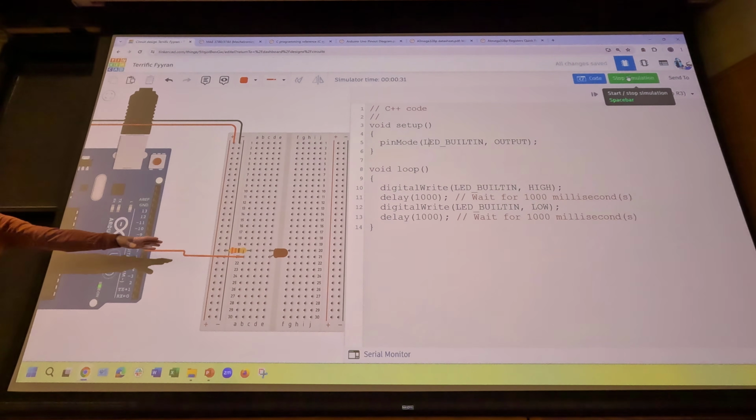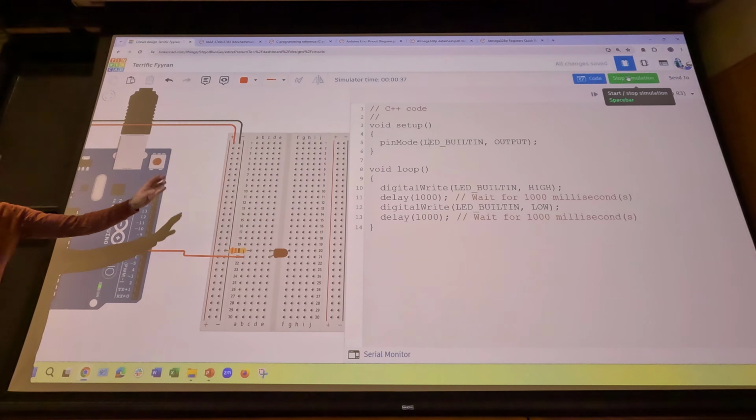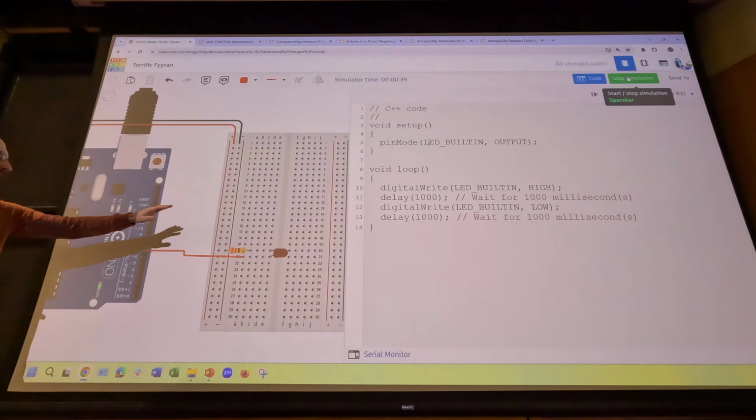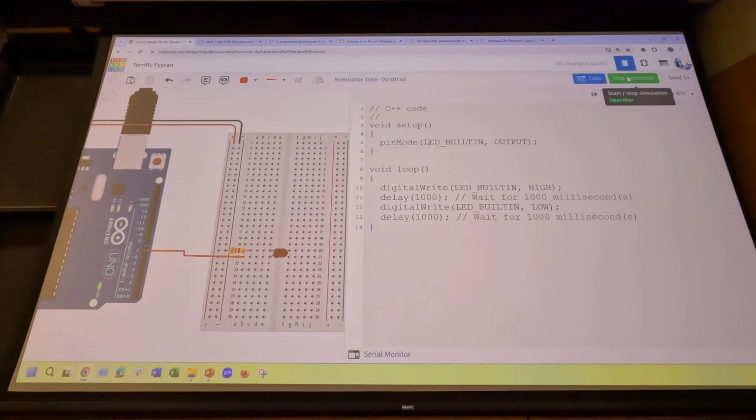If there is nothing connected to your Arduino and you just go to File, Examples, Blink in the Arduino IDE on your computer, this should work. Okay, if that doesn't work, then there's something wrong with your USB communication or something wrong with your Arduino board. So remember that as a fallback, but we're not going to do that because we're not using Arduino functions in this class. We're doing it the hard way.